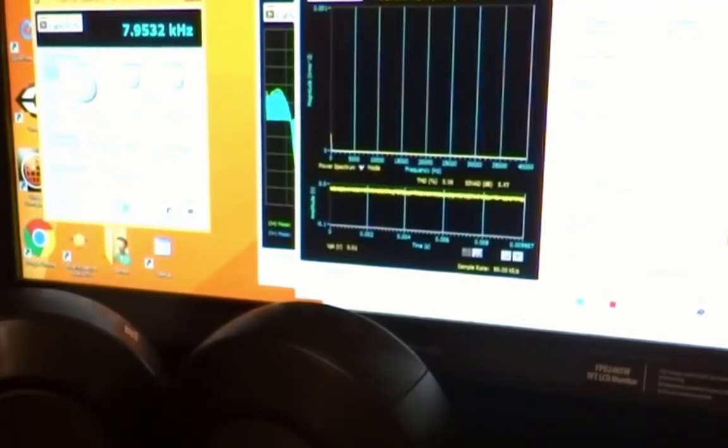Now, an important point to make is, this is a place where not having that filter cut off, or not having that low-pass filter, becomes important, because it's not necessarily the case that we're having information smearing on top of each other because the carrier is too low. We may just be in a region where that extra high frequency copy becomes audible. And I think that's actually what's going on here.